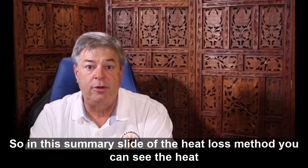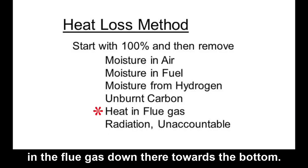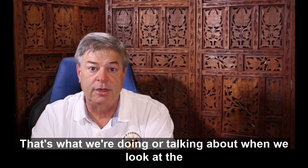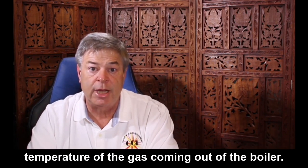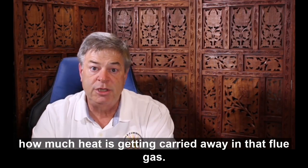So in this summary slide of the heat loss method, you can see the heat in the flue gas down there towards the bottom. That's what we're talking about when we look at the temperature of the gas coming out of the boiler. We can calculate the air in versus the gas out temperatures and look at how much heat is getting carried away in that flue gas.